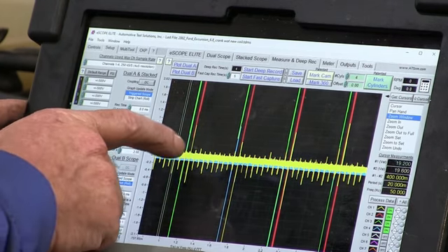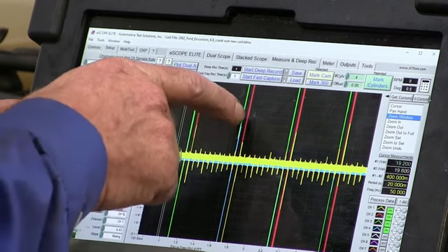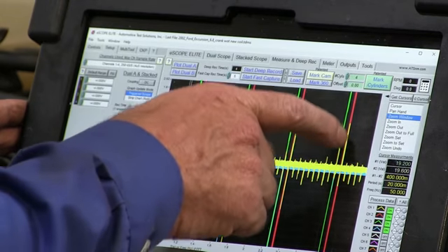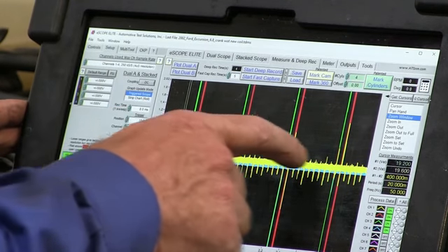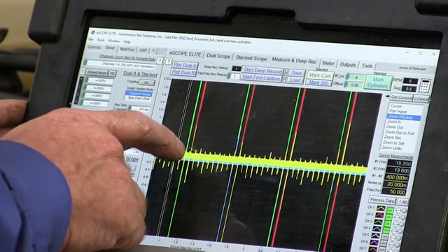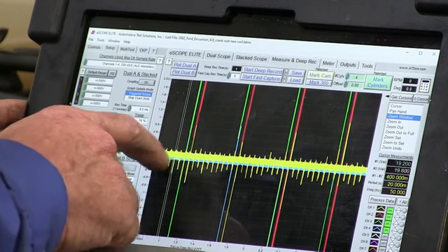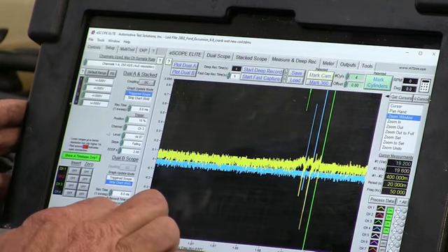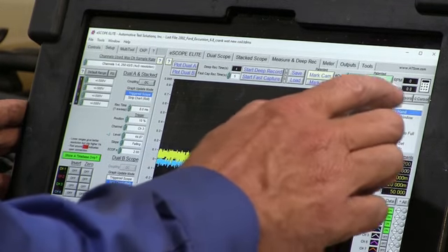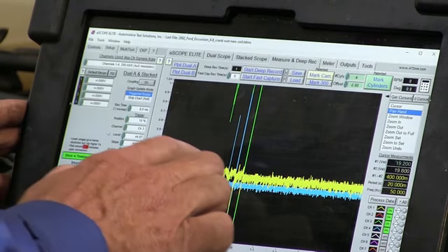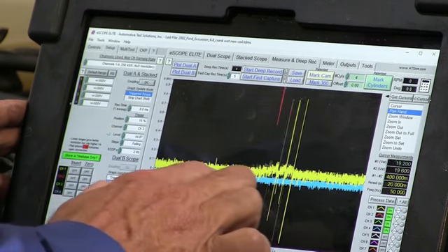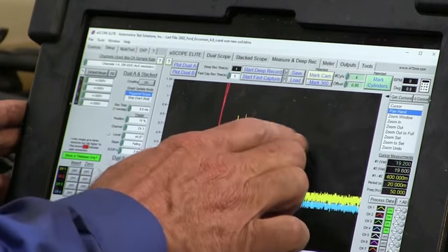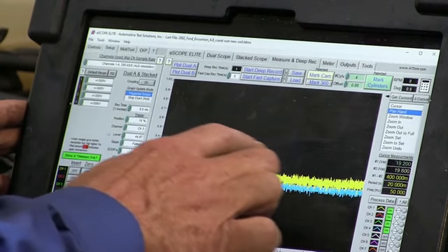So now the biggest strike down is from the number 1 coil, and we saw some of that earlier, but now the number 1 coil is getting more energy into that sensor, but at least we don't have 3 large strikes in a row off of the number 9. So we can see right here that's where the number 9 coil was, and it doesn't have the great big ones, but we do still have 3 pretty big ones off of 1. So we're going to need to look at that.